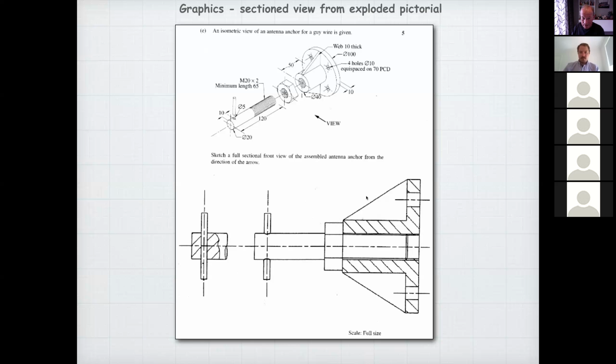And another thing that is really good to know is see where these flats on the hexagonal nut go. They go between the threads there. Now, normally you would be expected to do this, right? You set up your compass and you draw a semicircle like that there.